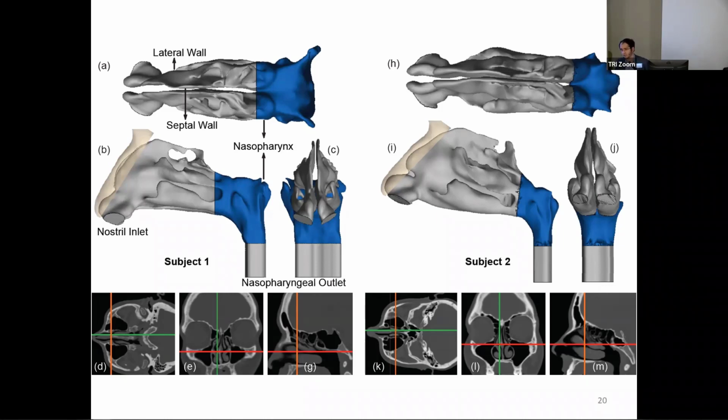But here, particles are supposed to stand in for the drug particles, and hence the physical parameters should be modulated accordingly. Also, this comes out in a plume, of course. When we model the inhalation process, there is no plume-like conical injection. But here, since we are doing intranasal sprays, we need to make sure that the drug delivery parameters are replicated accordingly.